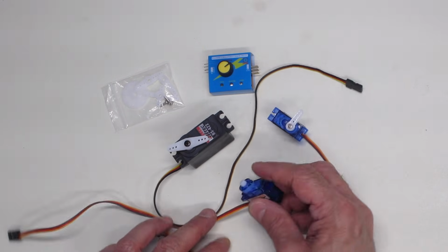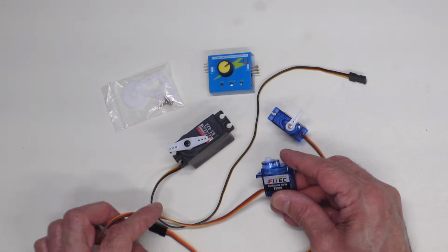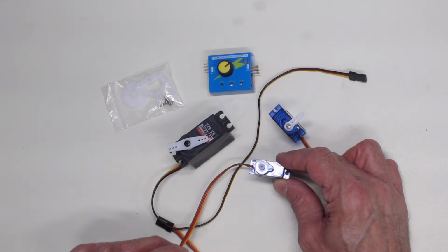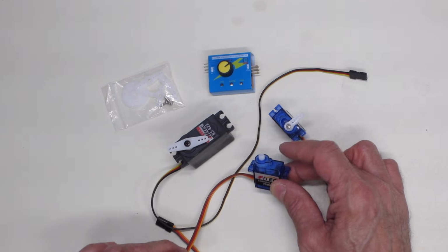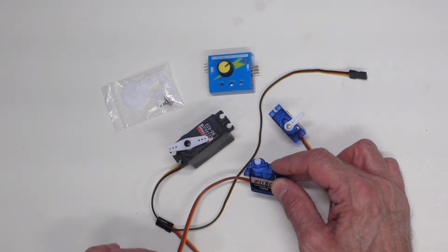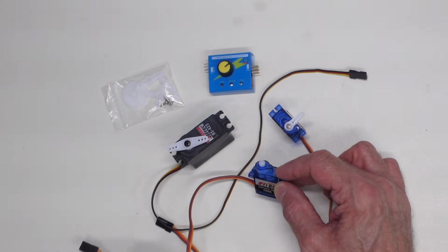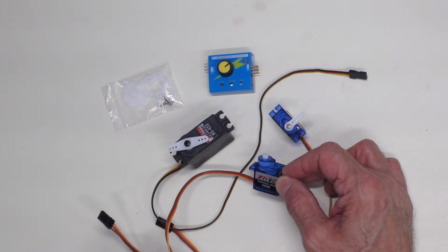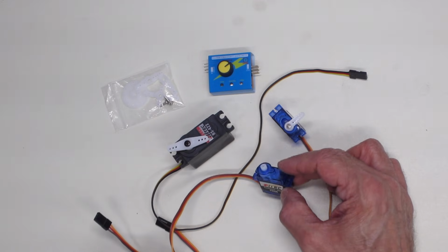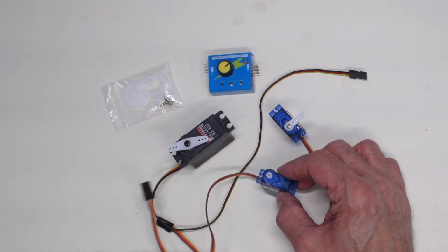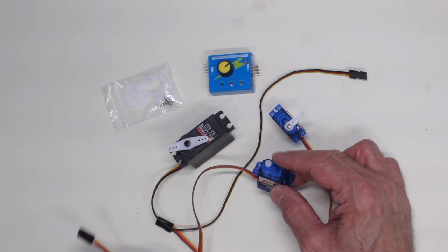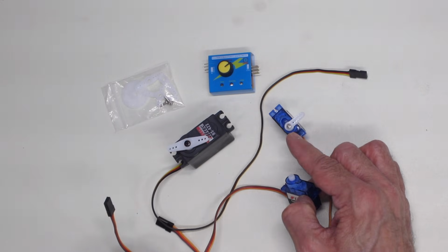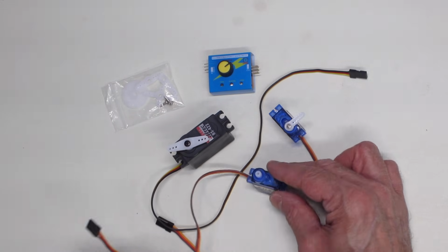Now this one looks a lot like an SG90, but actually this isn't an SG90. It's a modified one, and these are commonly available, and they're called continuous rotation servo motors. These are not the type of servos we're going to be using today. A continuous rotation one can continually go in 360 degrees, and the pulse width modulation signal determines the speed, not the position on these motors. So because they look alike and because they have the same connectors, be aware that these motors, which are marked as continuous servos, are not the same as these servos which only travel from 0 to 180 degrees.